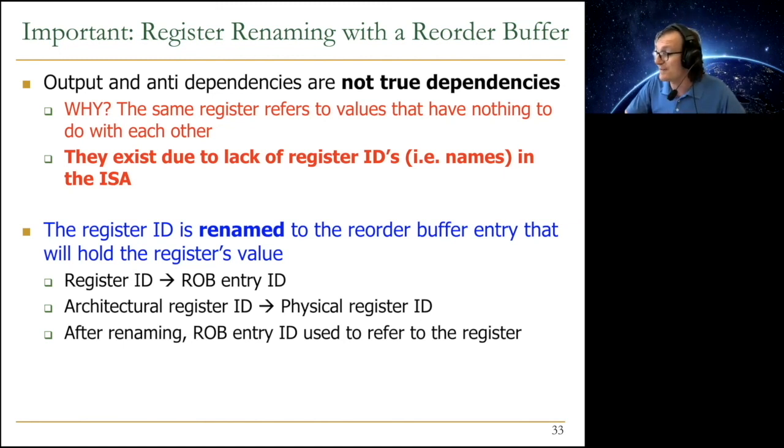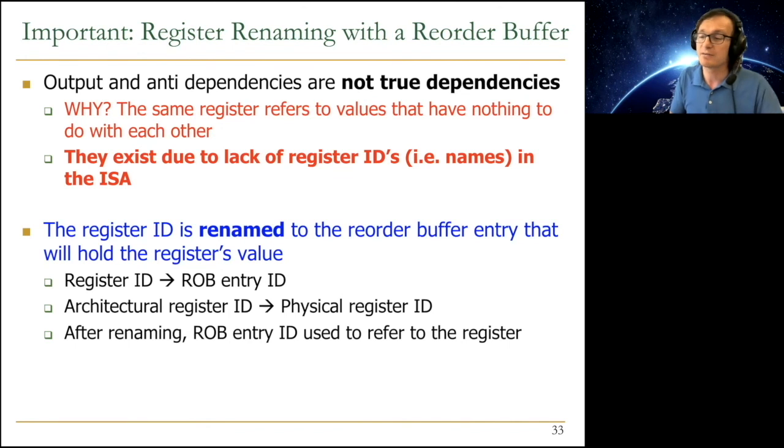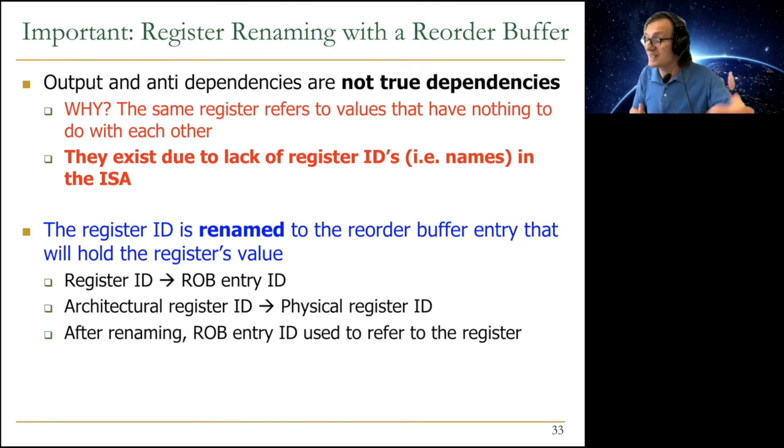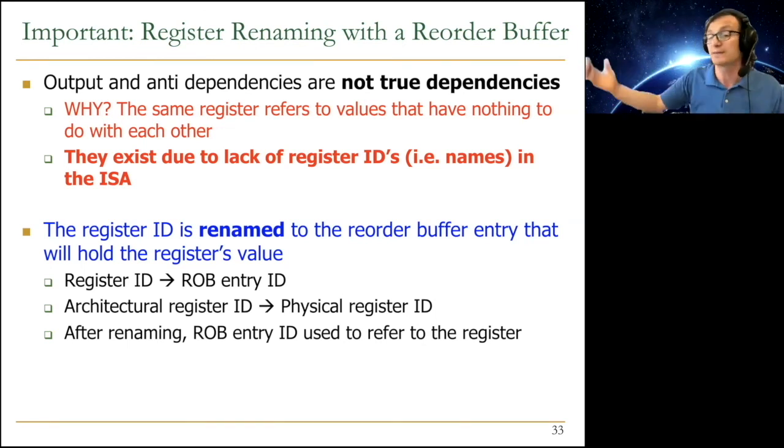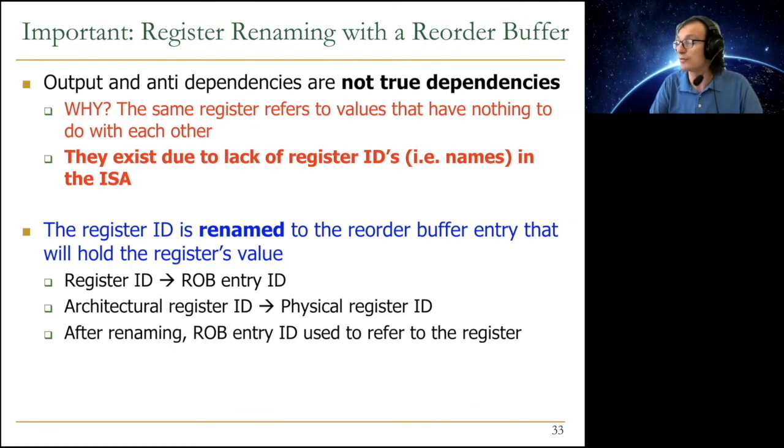Is there a performance benefit to the reorder buffer? Not exactly. What we're doing right now is really providing precise exceptions, precise semantics, and trying to provide the benefits of forwarding the values in a good way. So there are really no performance benefits the way we discussed it so far. But later on, when we introduce out-of-order execution, the whole machine will provide performance benefits, as we will see. The register renaming concept provided by the reorder buffer will lead to performance benefits later, but not right now. So that's a good question.